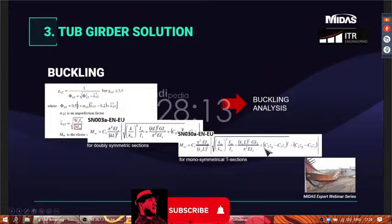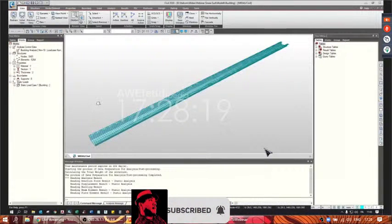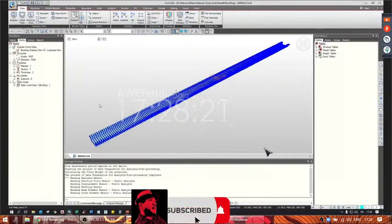We prepared a model of the tub girder we talked about. We import the section, in this case, from AutoCAD as a line element, and then we extrude it to realize the girder as a plate element. It's important to create a plate element because with a line one, we cannot catch all the possible deformation of the beam.